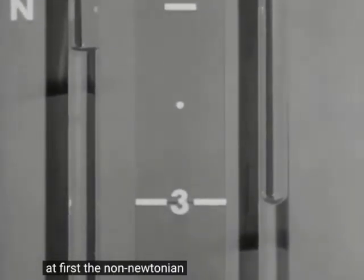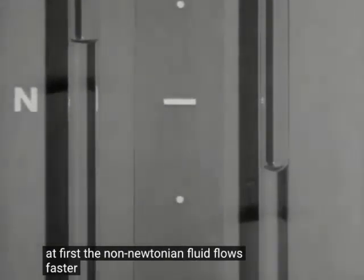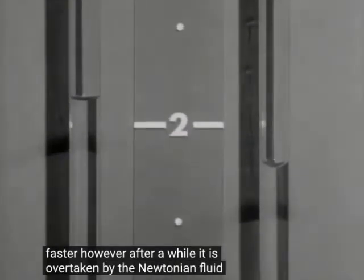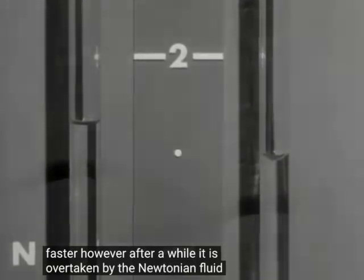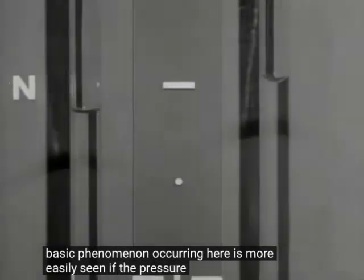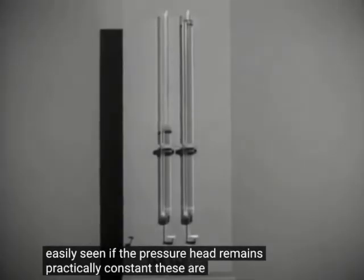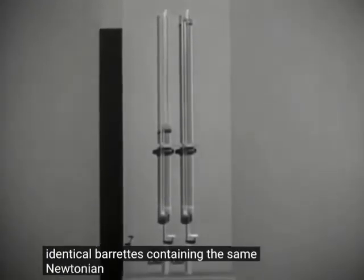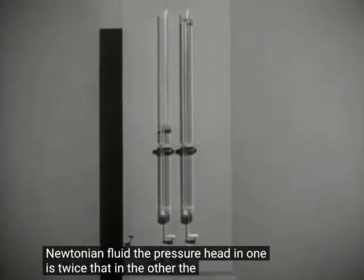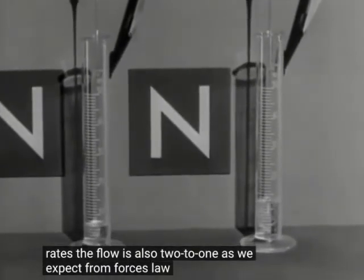At first, the non-Newtonian fluid flows faster. However, after a while, it is overtaken by the Newtonian fluid. The basic phenomenon occurring here is more easily seen if the pressure head remains practically constant. These are two identical burettes containing the same Newtonian fluid. The pressure head in one is twice that in the other. The ratio of rates of flow is also 2 to 1, as we expect from Poiseuille's law.